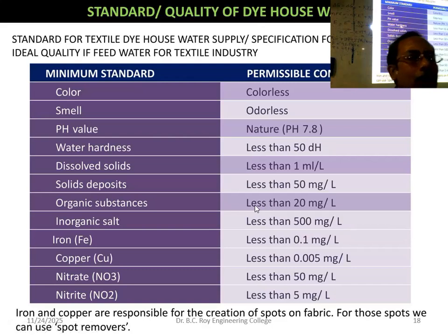And regarding iron also, I should say that in the bathroom water, the pipelines get damaged very soon if there is iron contaminated water. So iron is also very bad, like hard water. What you find is that in the pipelines, at every junction there is a brown color deposition and it gets damaged very soon. Metallic pipes, particularly GI pipe.